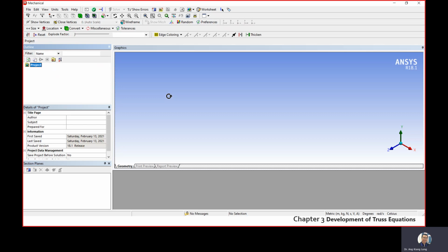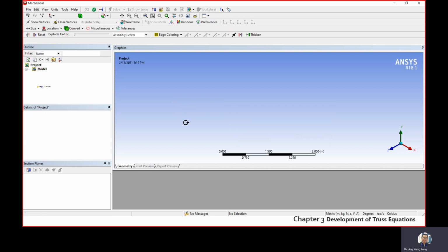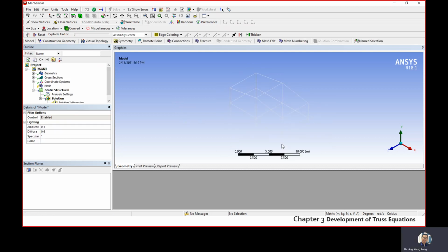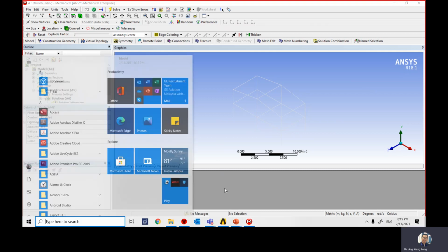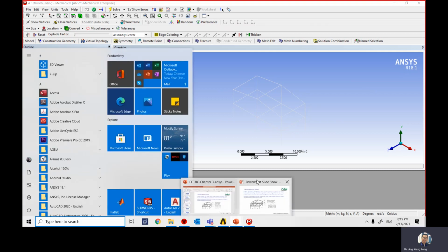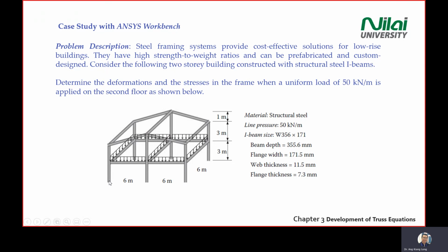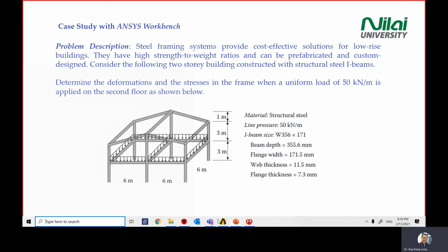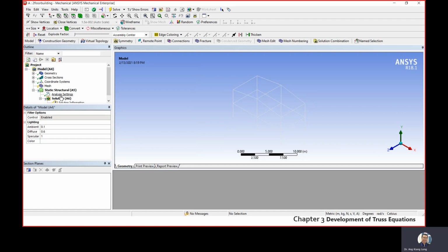So we're going to have a fixed structure while waiting for it to load. So this is our structure. The line is in white color, a bit difficult to look at. So we're going to put a fixed structure here, 1, 2, 3, 4, 5, 6 at the bottom of the leg there. So we're going to have some constraint below there.